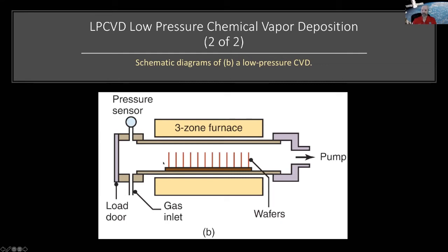Okay, and then the wafers usually are stood up with some space in between them. That way, when you pump in your gas, a chemical reaction occurs and puts a material down. A common material that we use is polycrystalline silicon. That's why we learned about polycrystalline structures, right?